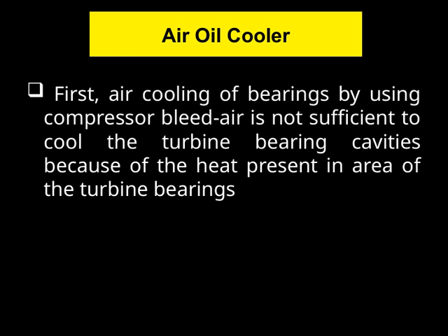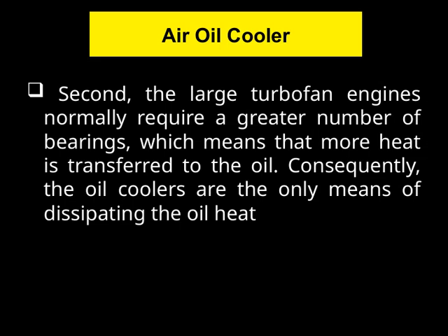That's where the air oil cooler comes into play. It's essential for maintaining proper bearing temperatures and ensuring the reliability and safety of the turbine. This highlights the importance of effective cooling systems in managing heat and preventing bearing overheating, which is critical for overall engine performance.